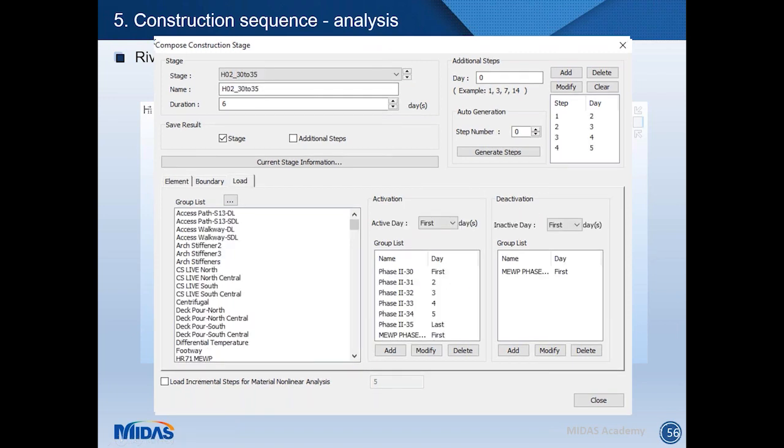The phase after the concreting is the restressing to get the end shape at opening day that we want for the deck. And so the restressing is simply done through the application of loads, very much in line with what was done for the first stressing. However, here I just used a slightly different technique.